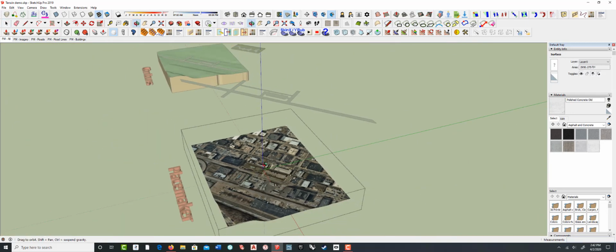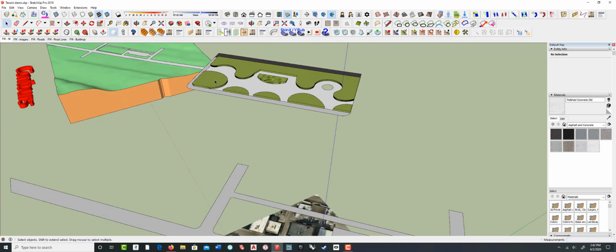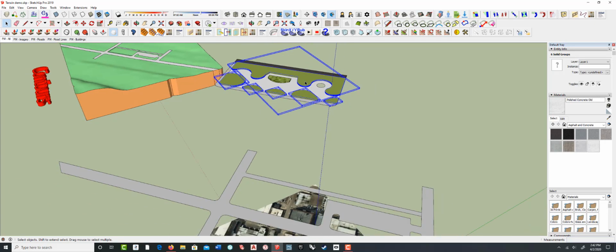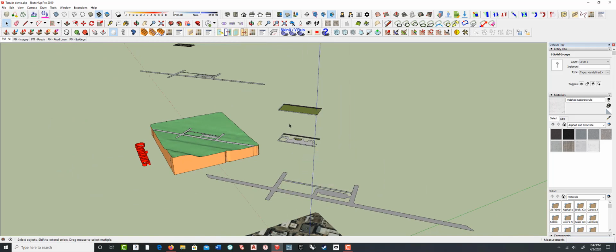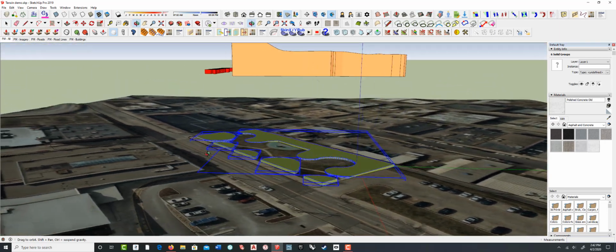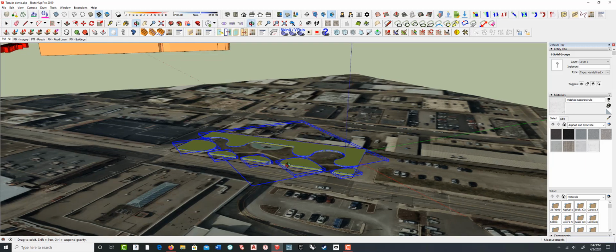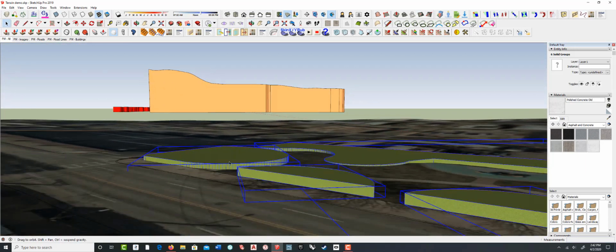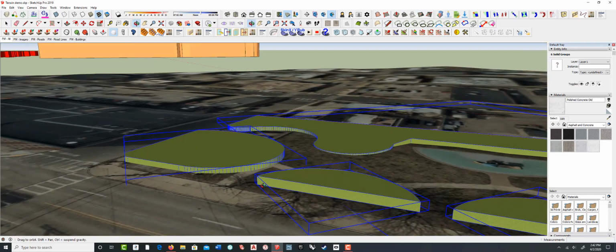And then what I would do is, since you're not going to really be manipulating that terrain very much, if this is my design layout, I could take these elements and I have a plugin called DropGC. It's going to drop it down to there first. Do it again. Okay, so now I've got these dropped down on that surface, but I'm still outside the group. I guess I could still stay outside the group to do this. That maybe makes more sense. And I can just go in manually with the move tool, hit the up arrow. SketchUp likes to do that too.